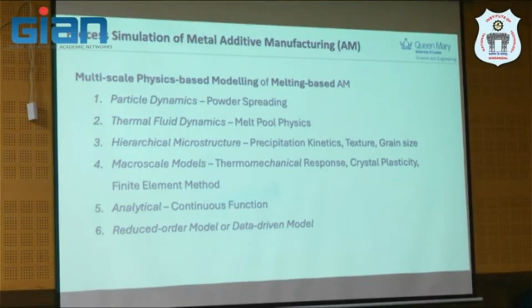Some companies approached me now, asking how the way we atomize to get quality powder can be simulated as well, because they want to know what happened and how they can get rid of oxide, for example, or scale, whatsoever. But if I'm talking about powder-based fusion, which is spreading the powder, some research is going on in particle dynamics, spreading, sweeping process. So they want to understand the packing density of the powder. So they use discrete element calculation. Again, this is classified as the modeling of additive, but it's not what I am interested in.